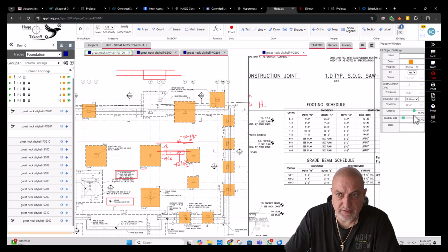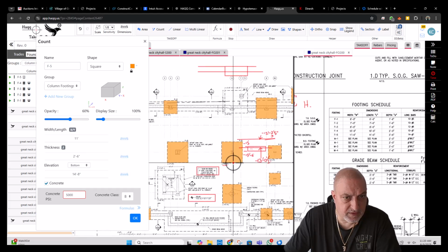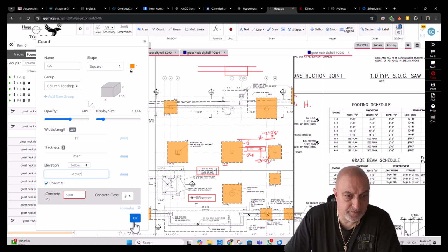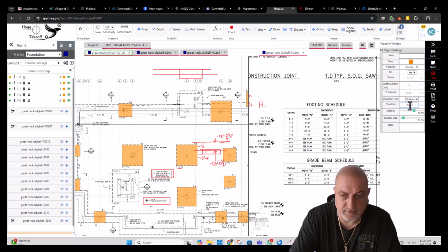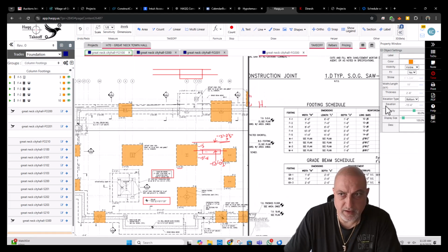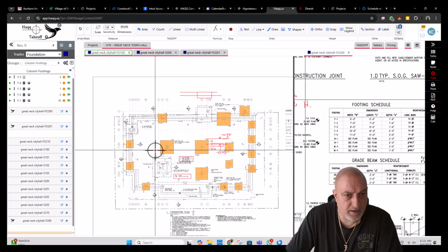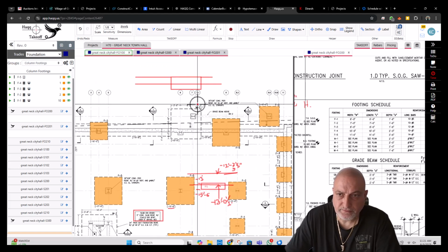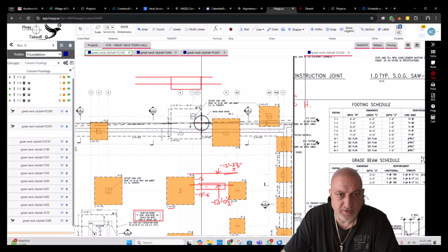And this one added, actually we had this wrong. Not the plus. Let's do minus, we're supposed to put minus elevation on minus 15.6. Let's change this again. Minus 17 feet 2. And minus 17.6. Now we're good with the elevations. We have to check the same thing on this. Actually, I could show you on the 3D. We'll do that when we come back to the continuous footings.